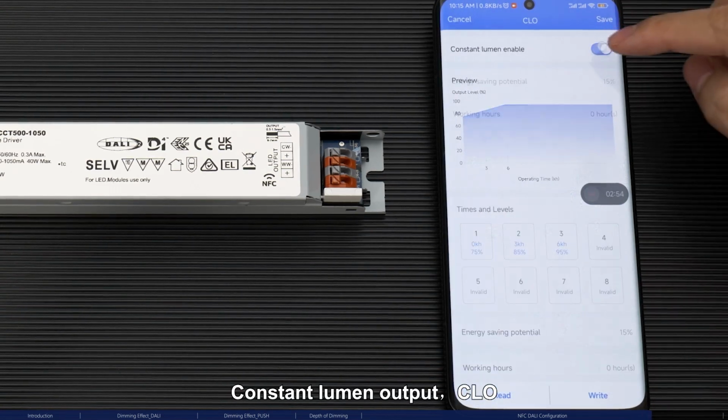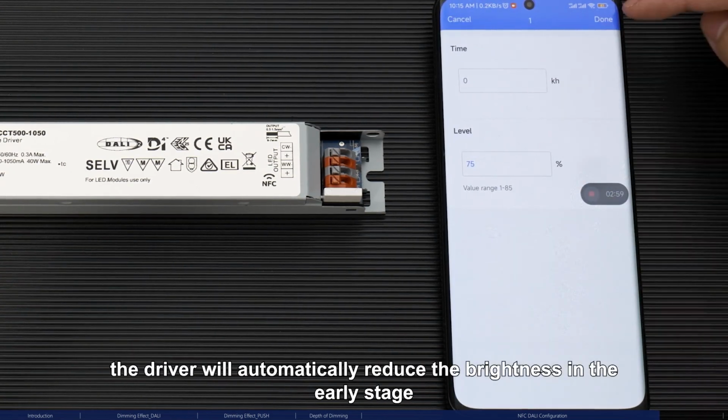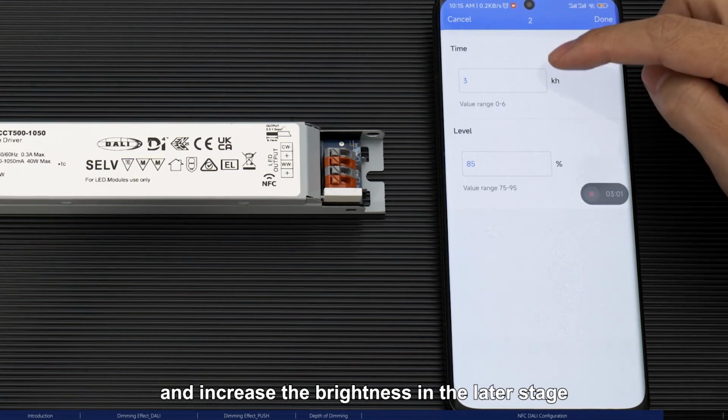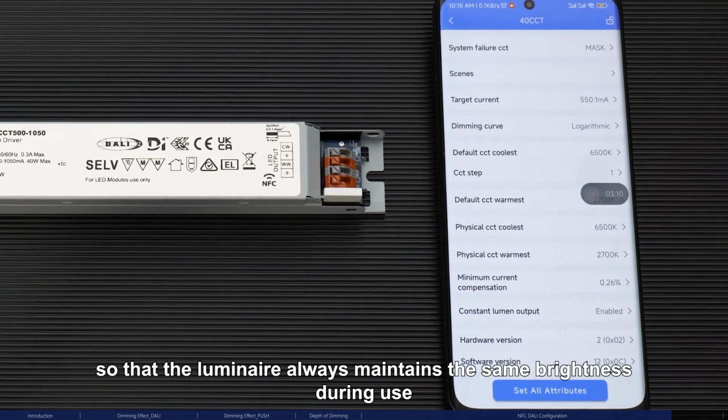Constant lumen output, CLO. With CLO turned on, the driver will automatically reduce the brightness in the early stage and increase the brightness in the later stage, so that the luminaire always maintains the same brightness during use.